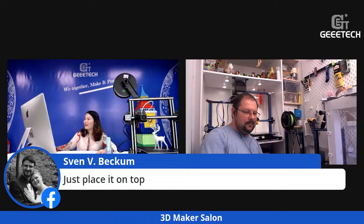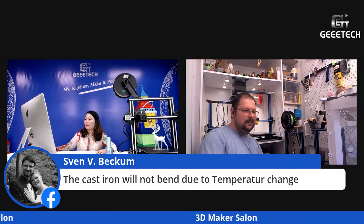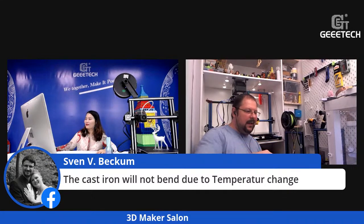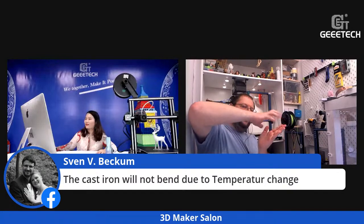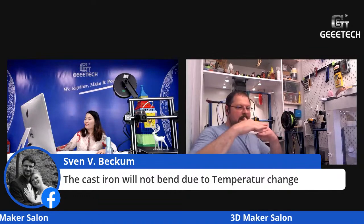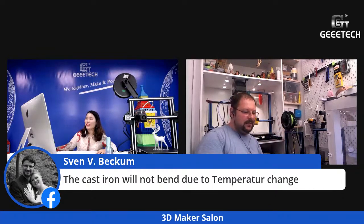Okay, just place it on top, and the cast aluminum will not bend due to temperature change. Exactly what I said, because it has the same temperature property as the heated bed. And if you stick a glass to an aluminum sheet, the glass will expand much slower than the aluminum, and if this is a sandwich, then you will have a wavy bed. But if the two materials are the same, they will expand the same way, every time. Very detailed introduction.